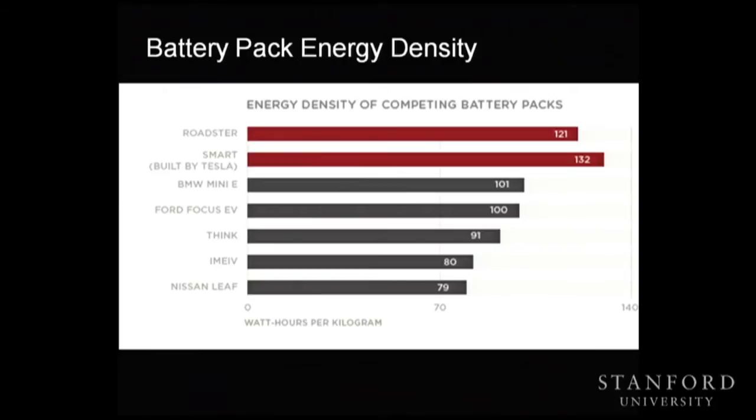When you take packs, and I don't know if this is even a real number, I mean, we talk about this number. People sometimes talk about these numbers and compare, but in reality, if there was any kind of competition around pack energy density, then it would stop mattering because people would arbitrarily move things in and out of the packs, because you can do that. It's mostly structure, electronics, cooling system, dead space. So you've gone from a cell at 200 watt-hours per kilogram to a pack which is on the order of half that.